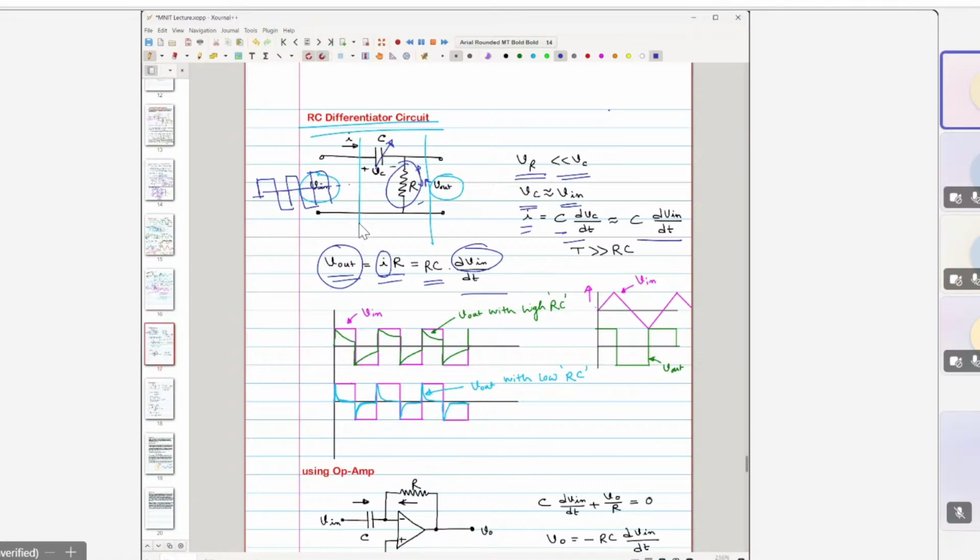Try to understand, because the potential across this capacitor is initially equal to 0, right? Then when this voltage, plus Vm, is applied, this plus Vm has to be applied across this resistor only, and this is the same voltage as the output voltage. So you will see the output voltage immediately shoot up to this V out, right? Okay, it reaches V out, fine. Then what? This capacitor has now been connected to this source of Vm.